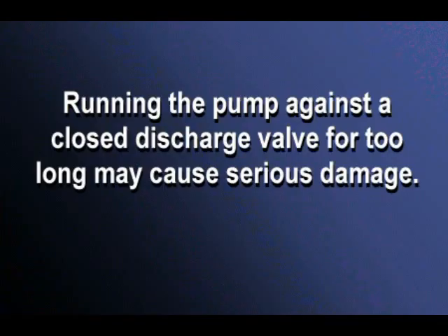Note that this can only be done for a short time. If the pump is run too long with the discharge valve closed, the water inside the pump will heat up, eventually changing to steam. This steam can cause damage, and in extreme cases even cause an explosion.